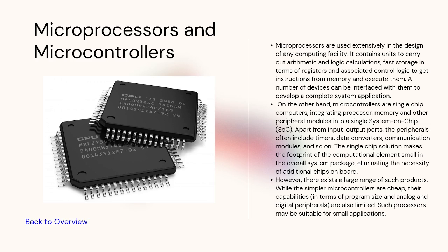And architecture is very important. The processor comes under the von Neumann architecture, where program and data are stored in the same memory. But the controller comes under the Harvard architecture, where programs and data are stored in different memories. The processor has some built-in memory. Examples of processors are 8085 and 8086, and for microcontroller it is 8051. The processor has an internal central processing unit. The controller has some memories or IO chips.